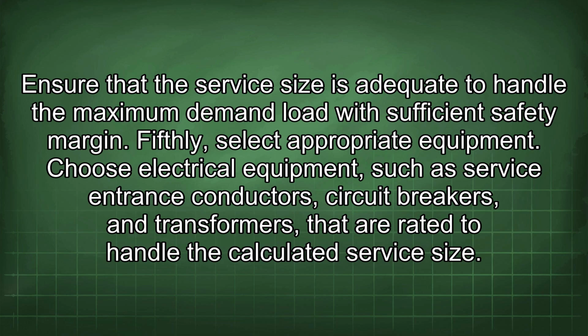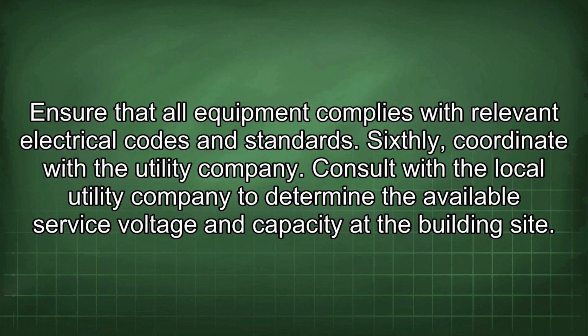Fifthly, select appropriate equipment. Choose electrical equipment, such as service entrance conductors, circuit breakers, and transformers that are rated to handle the calculated service size. Ensure that all equipment complies with relevant electrical codes and standards.